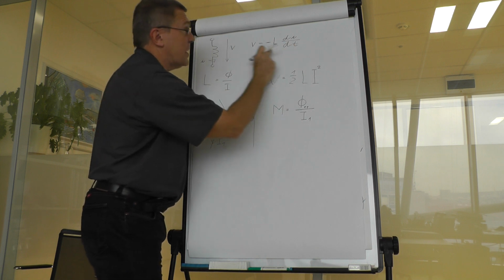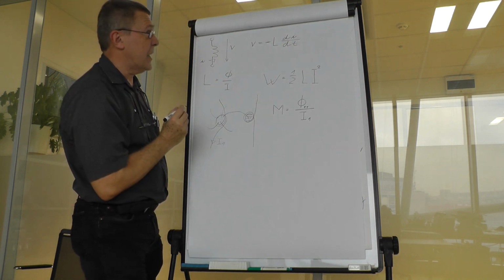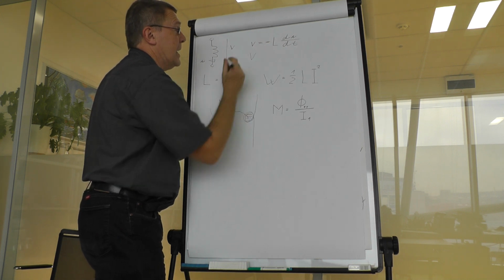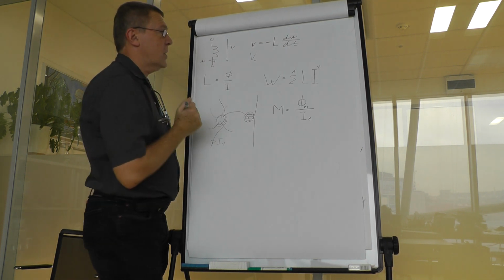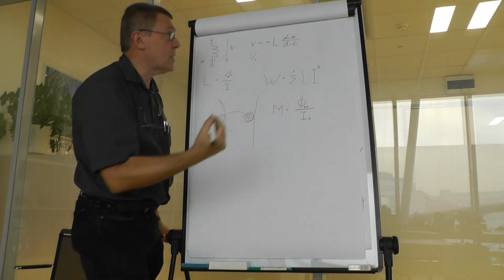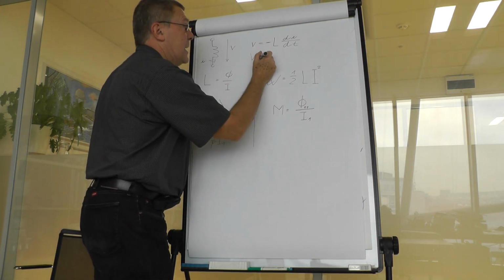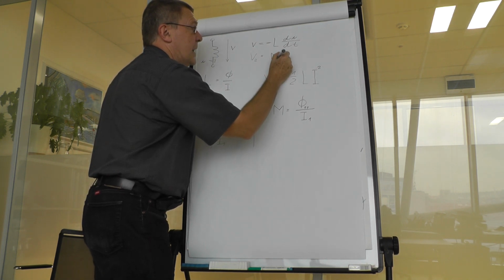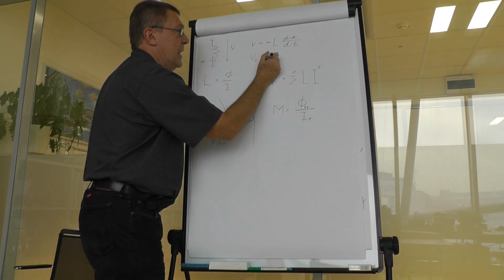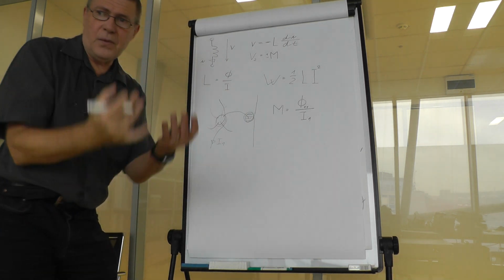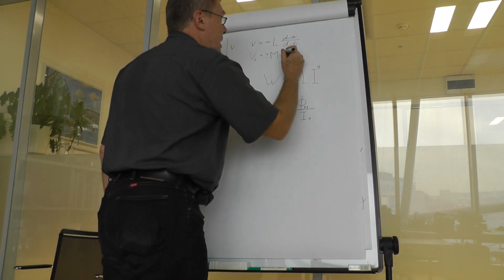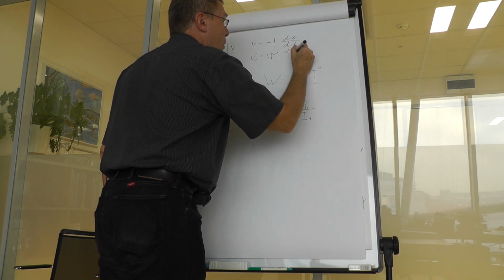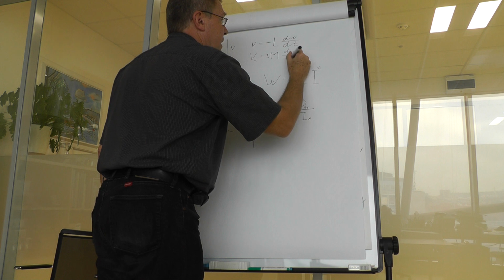use also the circuit theory definition, in circuit theory we can write down that the voltage in the second conductor that is induced by the change of current in the first conductor could be, depending on the orientation of those two coils, M di1 over dt.